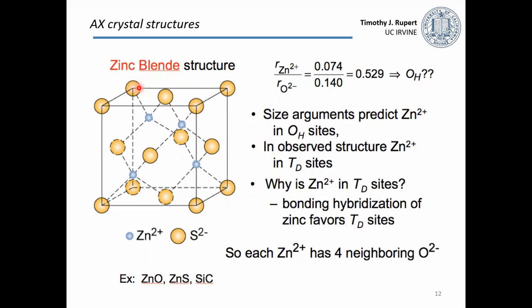What actually happens is it looks like these yellow atoms are on a face-centered cubic lattice. And these blue atoms are filling in 2 of the possible interstitial sites. And if we look, these are surrounded by these 4 atoms, and they're going to actually be tetrahedral interstitial sites.